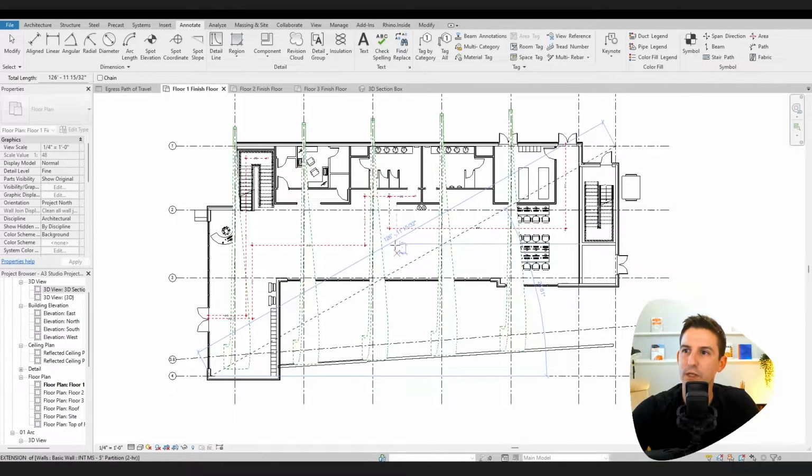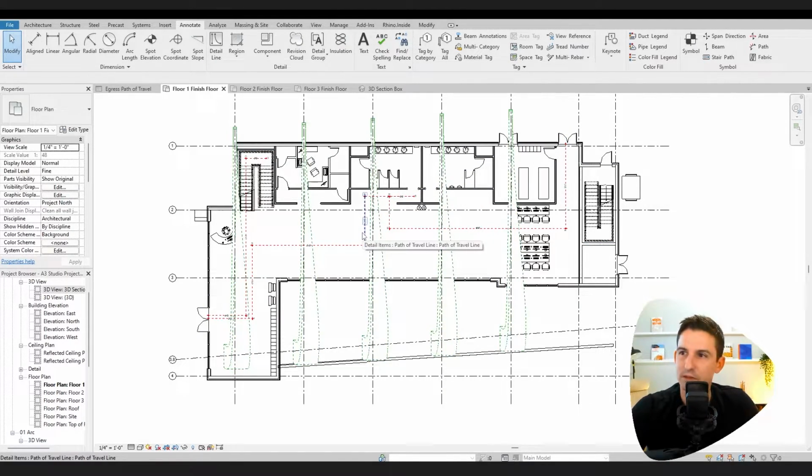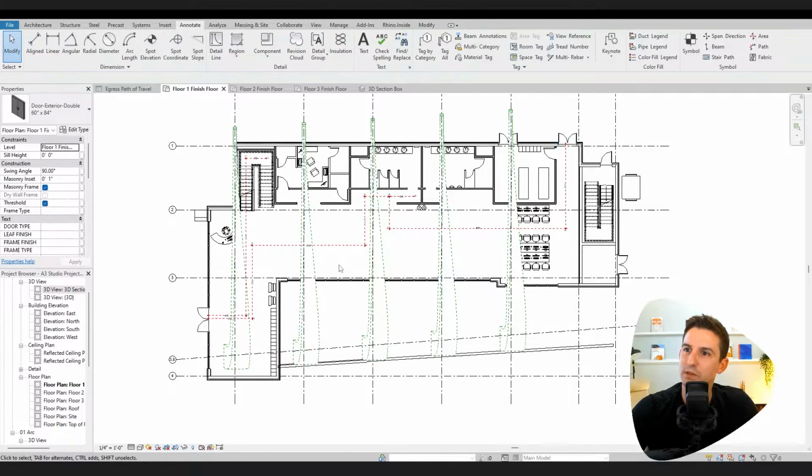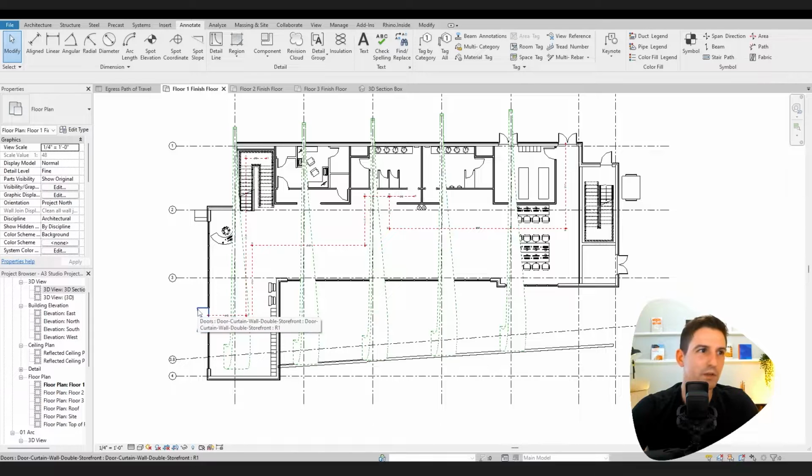And so if I just did 126 and 11 inches divided by the distance that these are apart, 109, I'm going to be well above half that distance, which is good. The idea behind this is that one fire doesn't block both exits at the same time. So we do need these 2 exits to be spaced out enough for them to be considered 2 different exits out of the building.